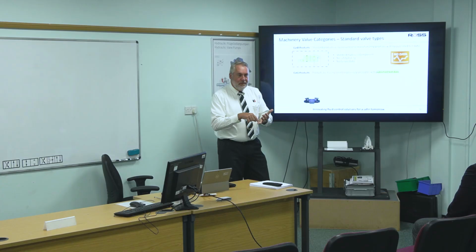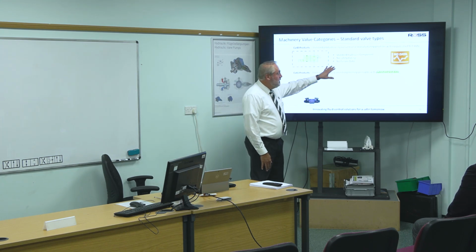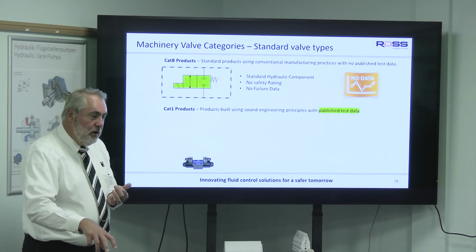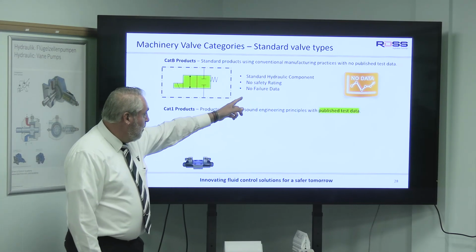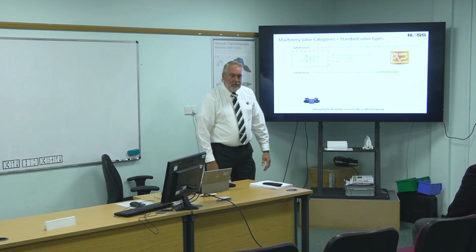What's the failure rate of this valve? So we put our valves on test and we run them until 10% of the products fail dangerously. And that's what we call a B10D value. So most of your safety companies will have a listed value of failure rate. If there's no failure rate and there's no monitoring, you're category B, you're at the lowest level.